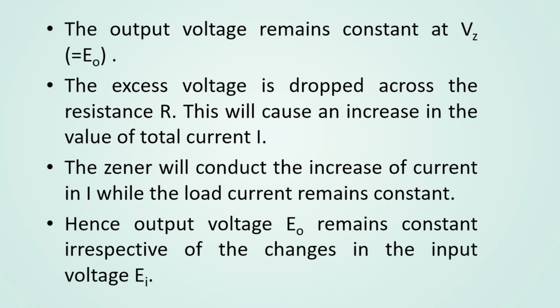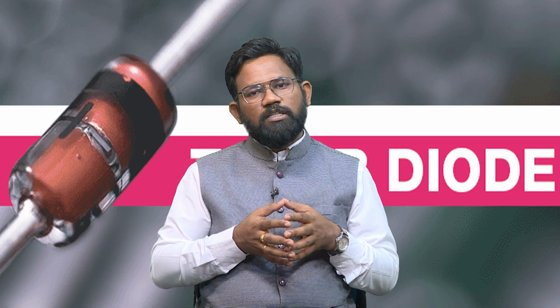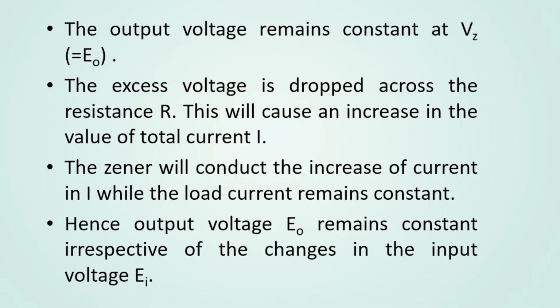So, the excess voltage is dropped across the resistance R. This will cause an increase in the value of total current I. So, the Zener will conduct the increase of current in I while the load current remains constant. The concept to make the load voltage constant is that even if the voltage or the load changes, the excess voltage is dropped across the resistance which is connected in series. The total current gets increased, but the voltage obtained at the load remains constant. Hence, the output voltage E naught remains constant irrespective of the changes in the input voltage Ei.